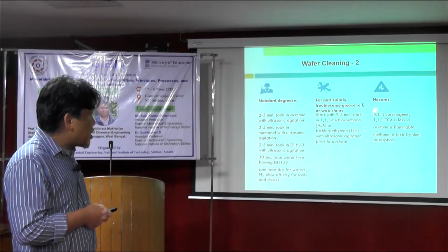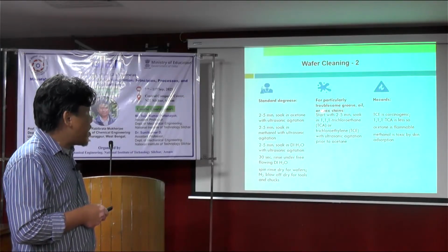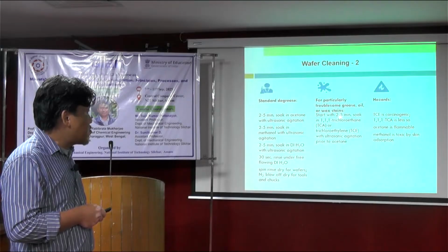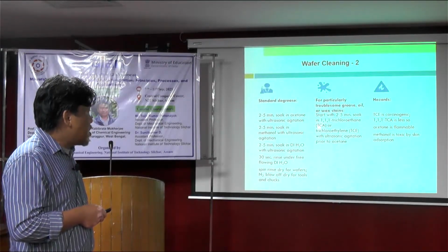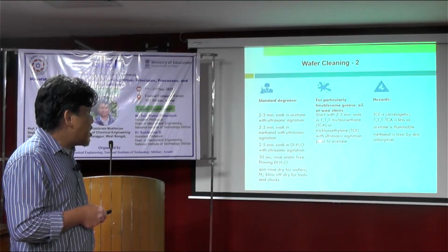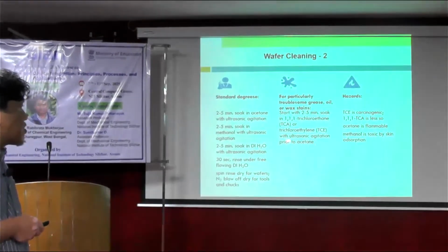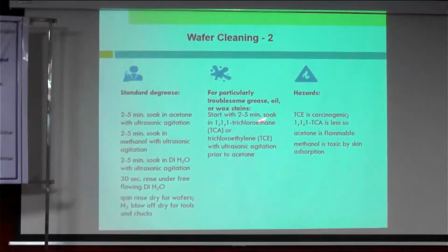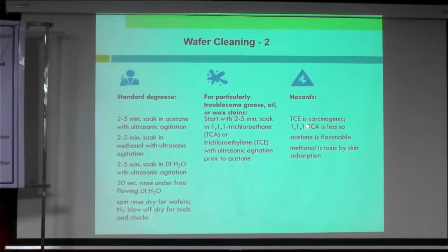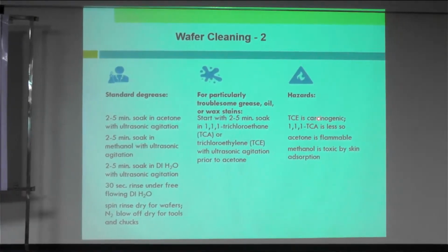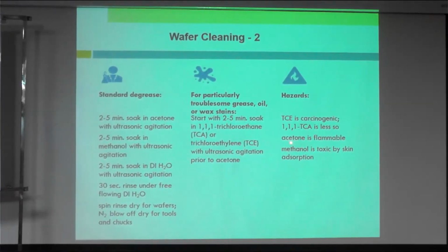For particularly troublesome grease, oil, or wax stains, start with a 2 to 5 minute soak with TCA or TCE with ultrasonic agitation prior to acetone. So this is a harsher process. TCE is a kind of carcinogenic, acetone is flammable, and methanol is toxic by skin absorption. So we must be careful. That's why in the clean room we use masks and gloves, etc. PPE.